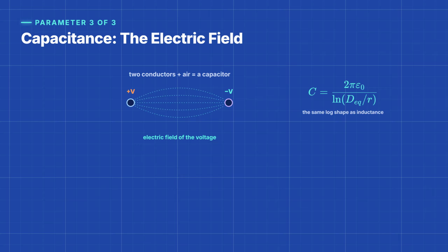This capacitance draws a small charging current, even when nothing is connected at the far end. On long lines, that charging current becomes important. It can actually make the voltage rise toward the open end, an effect worth watching.